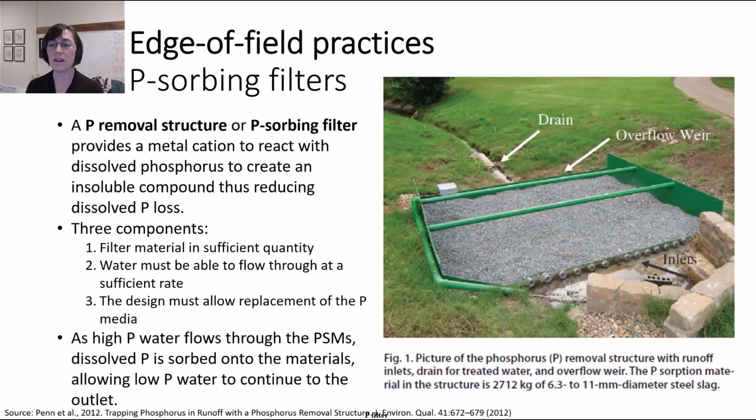And then the media will eventually get saturated with phosphorus because this is a chemical process that happens on the surface of the phosphorus-absorbing medium. All those surface sites will eventually get saturated, and so you have to plan in your design to replace the media. This is not a forever practice.